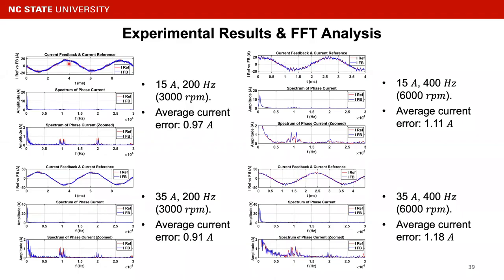So as we can see, the current feedback matches pretty well with the current reference. And also in the FFT analysis, the peaks in current feedback match pretty well with the peaks in current reference, which validates our theoretical analysis of 20 kilohertz switching and 20 kilohertz control bandwidth.